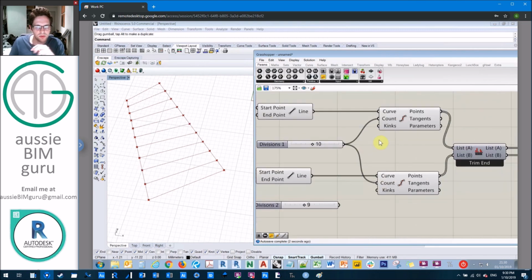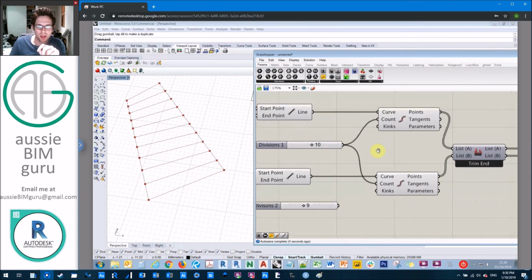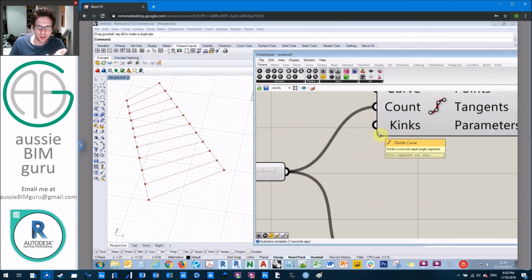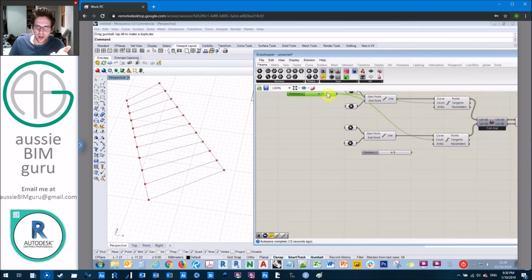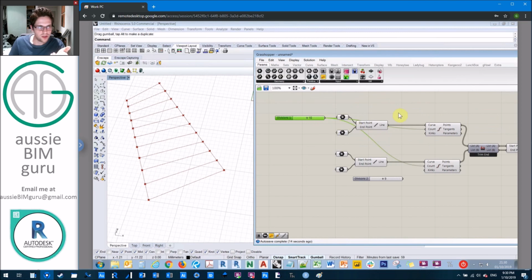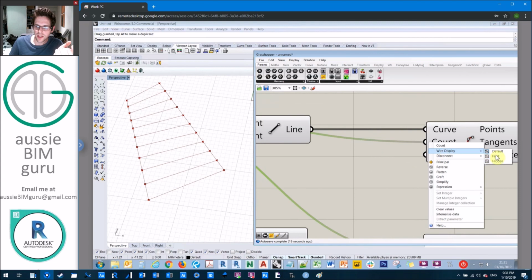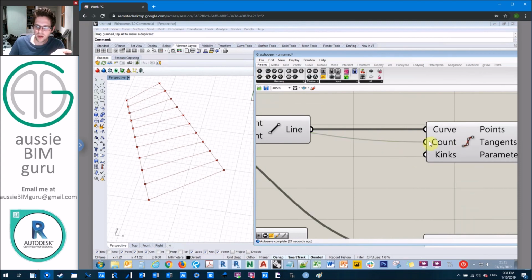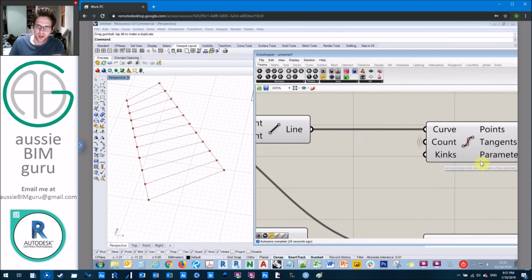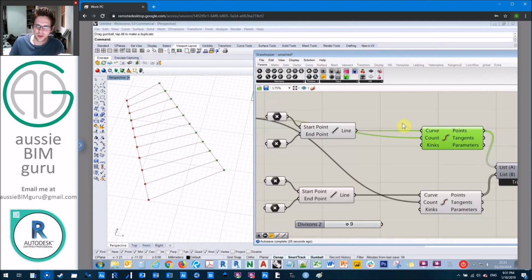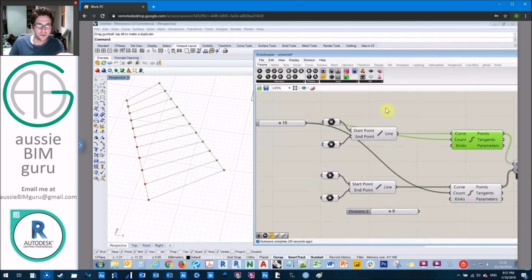It's important to notice too, and one thing I really like about Grasshopper is you can change the way the wires work between nodes. So let's say this node is a long way away and it's going through all my nodes and it's very hard to see where it's coming from. I might want to right click here and set my wire to a faint wire or even to a wireless wire, to a hidden wire, and it becomes a receiver. If I click on the node, it still shows me temporarily where it's going back to, but it makes it a little wireless symbol,